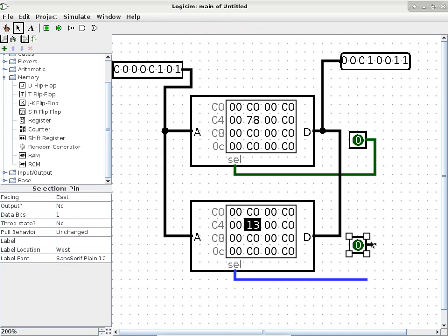So we'll hook up both at the same time first, okay? And you can see now the output pin specifies XXXX, which basically means no one is driving the wires, because we are feeding a 0 in both chips to the selection pin. In other words, you're telling both chips, don't pay attention, not talking to you, right? And you can even see that none of the location is selected, because if the chip is not selected, it does not even pay attention to the address bus. Are we doing okay so far with this picture?